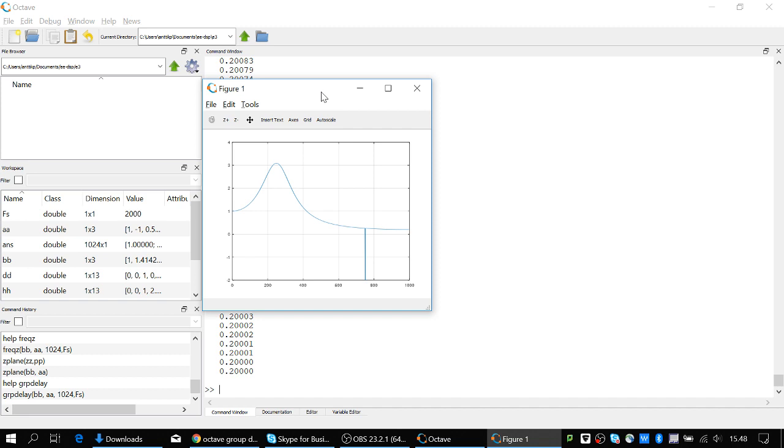And it shows that, okay, at 250 Hertz, which is exactly the same angle where we have this pole, we have a little bit more than 3 samples long time delay. But for example, the DC component only has about 1 sample delay. So it means that these different spectral components travel different time on that system. They come out at different times with the time difference.